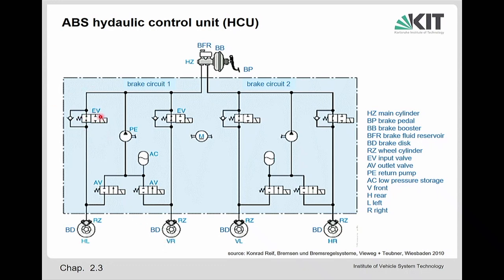As long as this is closed, there will be no contact between the brake pedal and the wheel brake. Yeah? But the driver needs always to have the control. If the driver decides braking activity should be stopped, then it should be stopped immediately. And so he leaves the brake pedal, and so we will have no pressure here anymore, but here is still a high pressure, and so we will have a release of the pressure over these valves. Yeah? Okay.